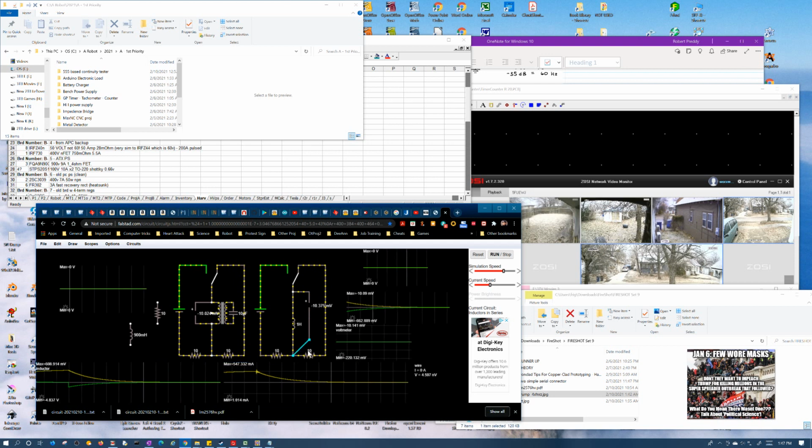But then when we had a higher resistance, like 100 ohms, we had that half an amp to charge it, but to discharge it, it's trying to maintain half an amp, but it's having to do that at 100 ohms of resistance instead of 10 ohms. So because of that, its voltage, instead of being 5 volts, has to be like 50 volts.